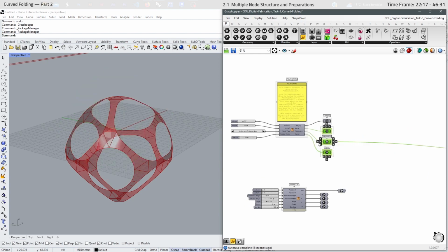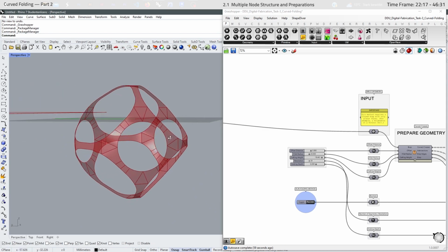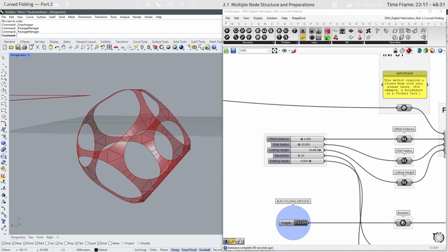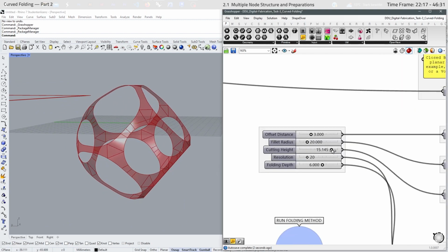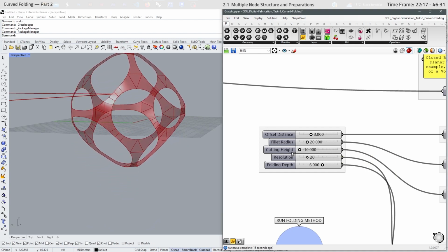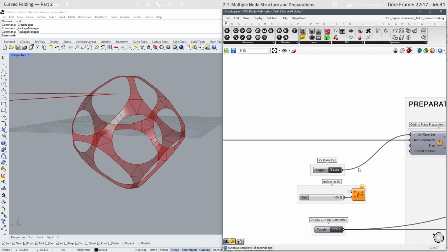With this script, you are able to create a whole polyhedron. But in our case, we want to cut the geometry at the XY plane. Here at the beginning, we can change the height where we want to cut it. If we don't want to cut it, we have to move it up. And you have to adjust something right here. It's just a small component, so you just have to disable this component if you don't want to cut through the XY plane. So you set it to false. But now we want to cut it through the XY plane, so I leave it at true.